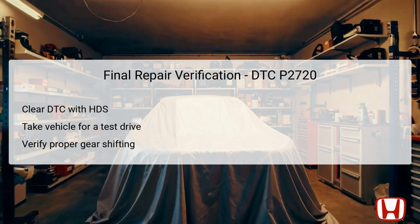During the test drive, closely monitor the vehicle's performance, particularly focusing on the gear shifting behavior. Confirm that the transmission shifts smoothly into all intended gears without delays or slipping. Performing this verification step ensures that the issue leading to DTC P2720 has been adequately addressed while providing peace of mind to the vehicle owner.